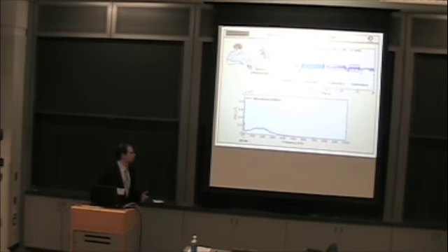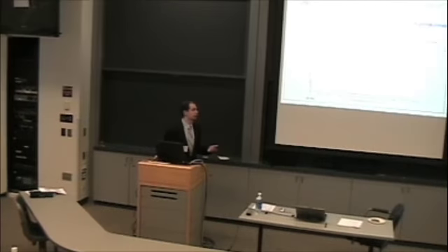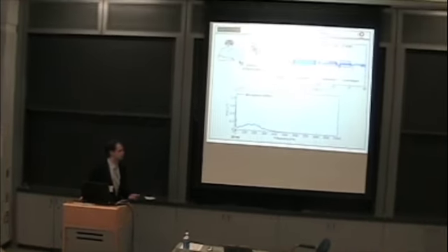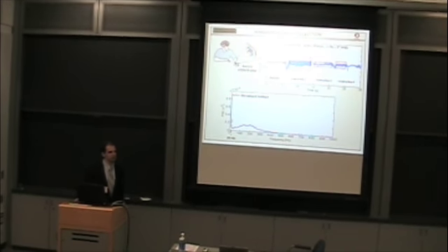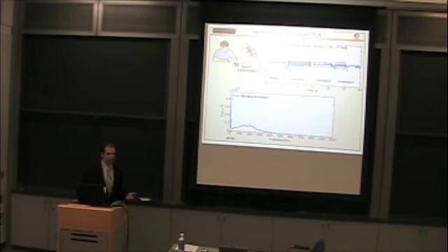Different spectra from different contractions were also compared, and in all cases, these low frequency components occurred below 20 hertz. So a 20 hertz cutoff frequency was chosen for this filter. As for the filter type, it was chosen to be a first order high-pass filter, and this was based on comparing step responses of different filters. The step response that overshoots the least, and therefore would distort the signal the least, was chosen.